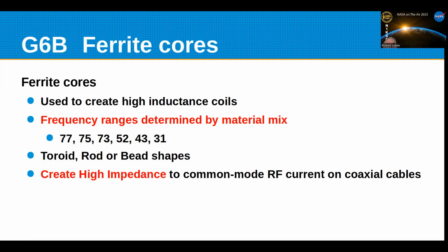The ferrites come in toroids, beads, which Byron has a bunch of them down there on East Coax. What's already in the bag? Yeah. And you can get them with the internal hole size about the same diameter as coax. Use them for common mode chokes.